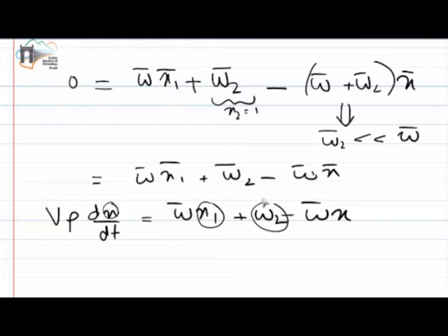Okay, so I need to have some kind of model or a simple representation in terms of transfer function, so that I can map these inputs to the output. Since these are differential equations, I also need to consider the initial steady state points. So if I subtract the initial steady state conditions from the last equation, I can do this easily, because dx bar/dt would be equal to 0.